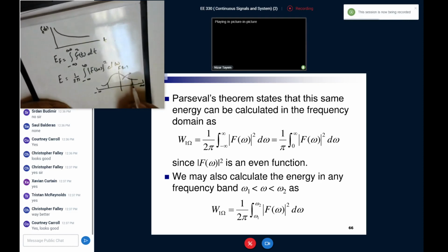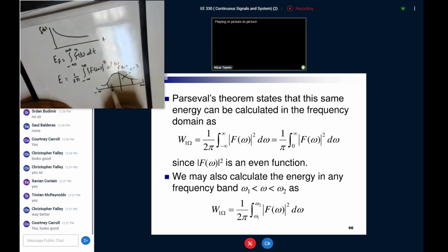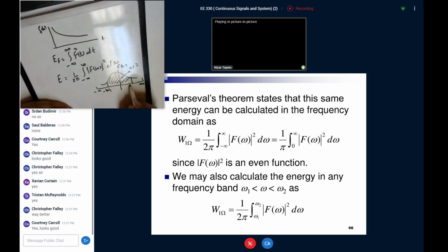So mainly we just need 95% of the energy. So 95% of energy is going to occur within this region. Okay. So in order to find the bandwidth required to send the signal, mainly we need to find out what? We need to find out minus omega 1 to omega 1 here. Okay. So I don't need to use the infinite bandwidth, right? Because the energy here on the tail is very small. So 95% of the energy will be enough. Okay. So that's one of the things here.